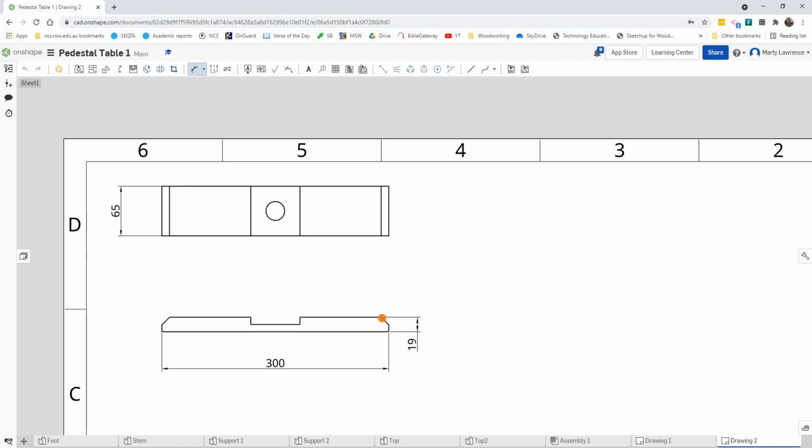These chamfers are going to be a pretty important thing to do. So you click once, move the cursor up. Notice if I move out at an angle, it'll do the angled dimension of that, the angled length, which is no good for us. So we want to get the vertical length. So it's 10, here to here.